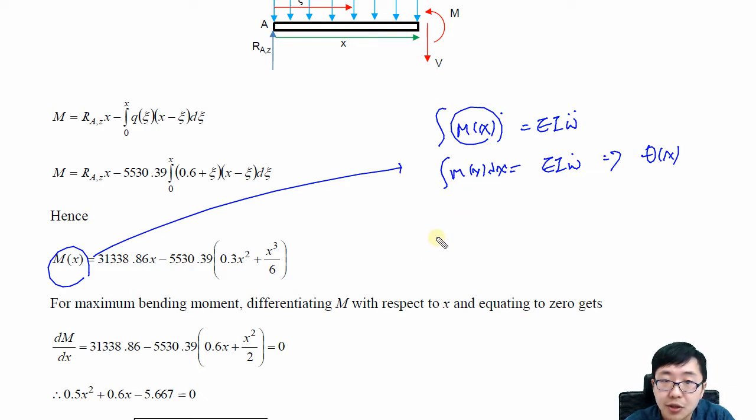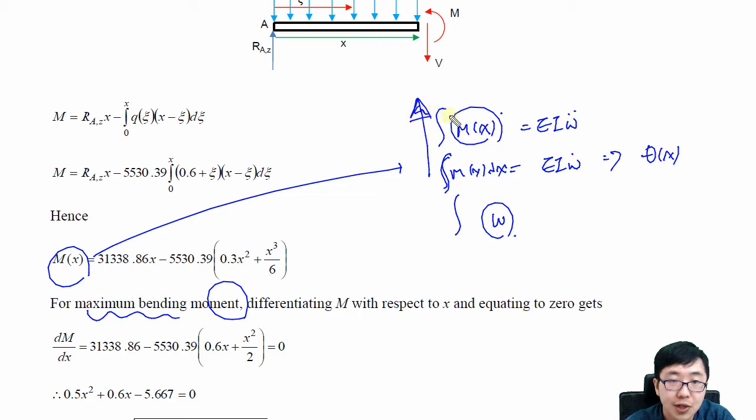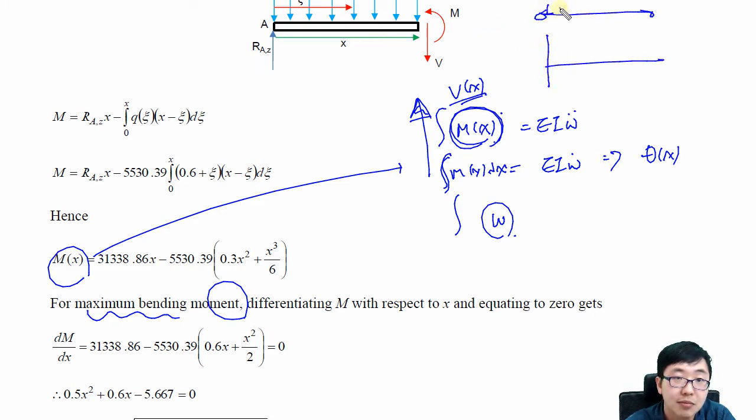Okay, so in here this is the integration way, and one more integration gives us the deflection, but what they need is the maximum bending moment only. So in this case they differentiate it. Mx differentiated gives the shear force, right? So for the simply supported beam conditions, if the shear force is 0, that means the maximum bending moment occurs.